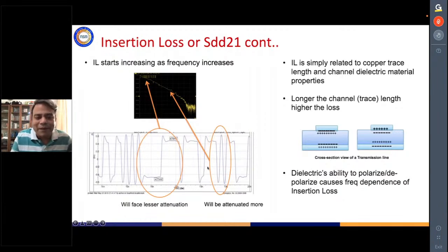When you look at that bit period or that bit diagram, multiple zeros followed by multiple ones is a lower frequency, right? Because the time period is high. When the bit pattern is a continuous sequence of zeros and ones, the frequency is higher. So you're actually transmitting a wide range of frequencies.